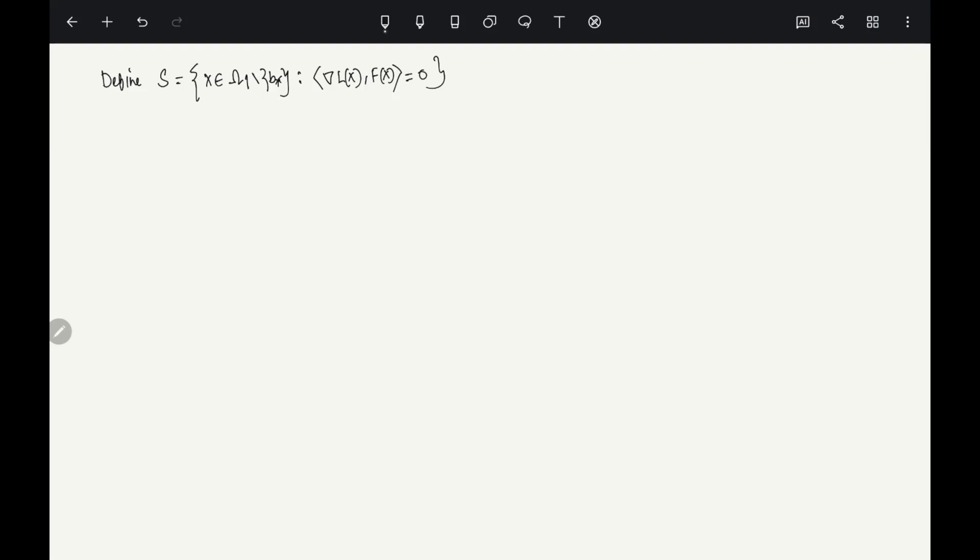In a Lyapunov condition, it is strictly less than or equal to 0, right? I need strictly less than 0 for asymptotic stability. So this is where it becomes 0. Basically the trajectory is not strictly decreasing, but it is monotonically decreasing. So specifically, what does this mean?